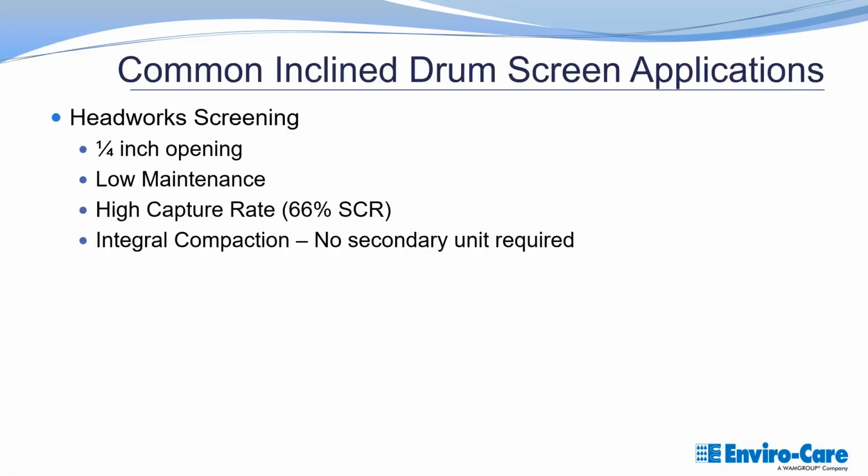So common applications for this, first of all, it does make a good headwork screen. It's very low maintenance. While it does have that big drum turning, that's about the only turning item on it, the drum and that auger. There's a couple locating roller supports, but otherwise there's very little moving parts. It makes it very low maintenance overall. It does have a very high capture rate, especially considering it's one of the combined screens.